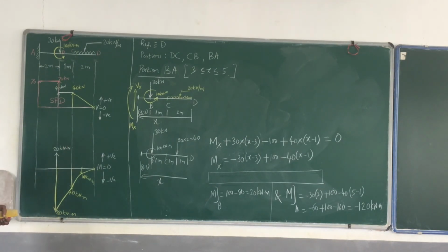Okay. What is the bending moment at point A? It is again negative. It is minus 120. It is more than 80. I'm sorry, I don't have a place here. Okay, I shall go beyond this 80 and draw it here and write it as 120. How does it vary? It varies in a straight line. So this is the bending moment.